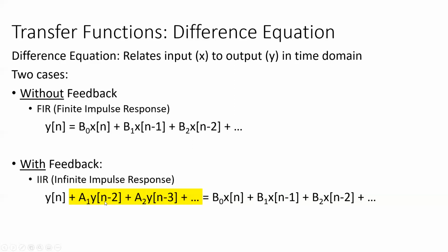So for that reason, it's an infinite impulse response, because it's always referring back to itself recursively. And so you can have functions that just go off infinitely and never die out. A finite impulse response is going to stop eventually after your input signal stops. So two different systems. They're both pretty good, useful for different things. It's just two flavors. The FIR is just with these coefficients as 0.